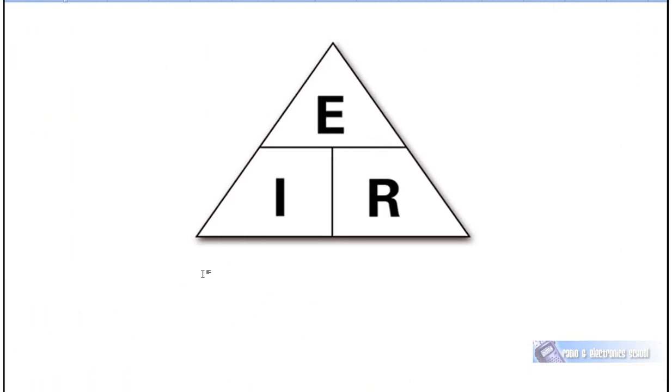Now, if you know any two of voltage, current and resistance, you can calculate the other. And a really handy way of remembering the three equations for Ohm's law, that doesn't include the power equation P equals E times I, is the Ohm's law triangle.